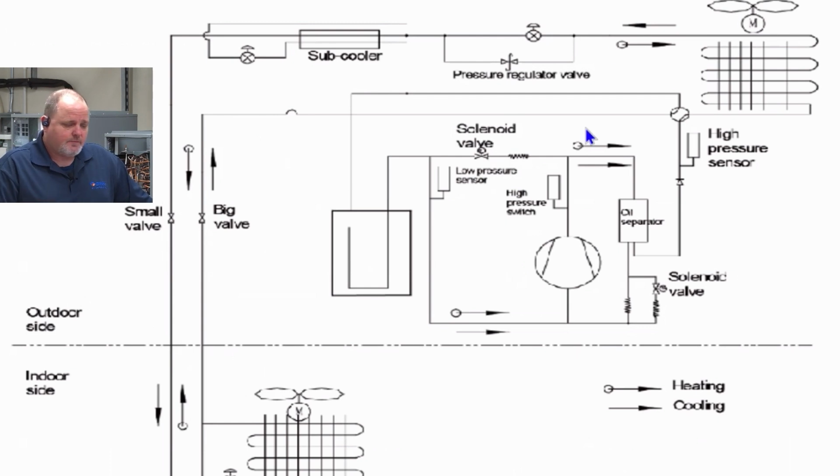Part of the reason why I'm bringing this up is because a lot of troubleshooting that guys call us about can be easily answered just by doing some simple inspection. The call I'm talking about was actually the fault of GREE. It was not the installer's issue at all. The solenoid valve on this EEV was dangling in the unit. It wasn't even on the armature of the EEV, so there's no way the motor could actually open the EEV. So this was 100% closed and pumping me down.